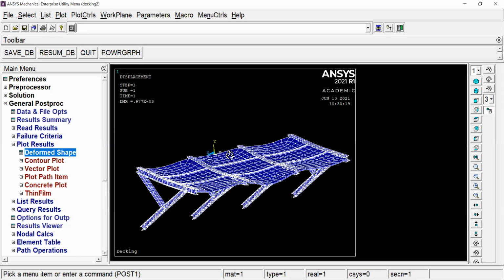We're not working with any solid elements, any brick or plate elements. We're not defining any contacts between surfaces. So this is just a very simple model, which is what we're expecting from you at this level. Just simple models, beams and shells are fine. We don't have to start offsetting and applying contact surfaces and stuff like that.